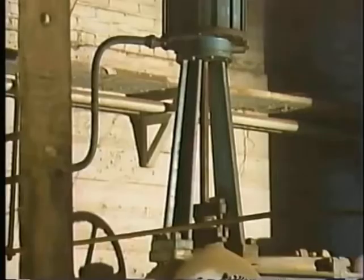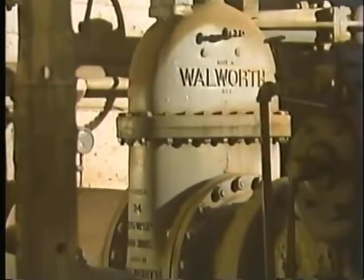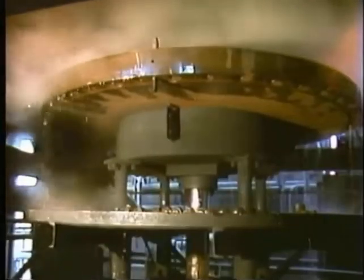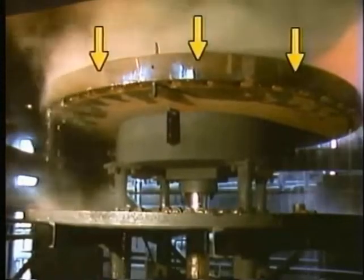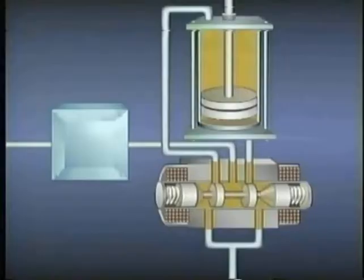For example, it may be necessary to operate an emergency system valve relatively quickly. On the other hand, a heavy load like this one may have to be moved quite slowly. Depending on the purposes of a hydraulic system, flow control valves may be used to control the flow of fluid to an actuator or from an actuator. We'll look at some different methods of accomplishing these tasks and why they're necessary. Then we'll take a look at how a flow control valve works.